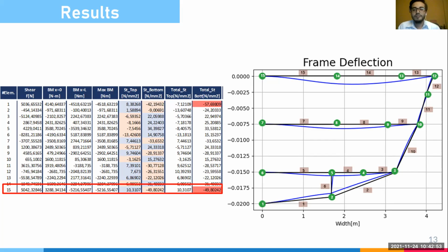At first we have to find that the element is a solid foundation, so it provides an almost perfect clamped condition. And we can see in the graph that there is no rotation, there is no displacement, and a negative bending moment is acting on that point.